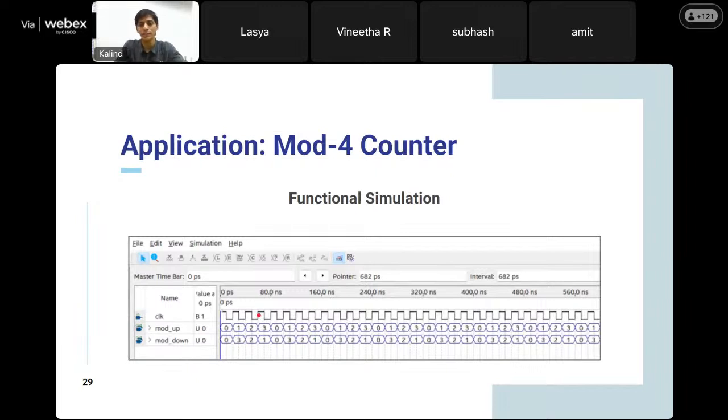The difference between CPLD and FPGA, as I had told before as well. There is one particular term called equivalent gates. In VLSI design, equivalent gates are nothing but the number of logic elements required to realize your logic circuit or logic design. In the case of CPLD, the number of equivalent gates is very high because you have lots and lots of AND and OR gates available.